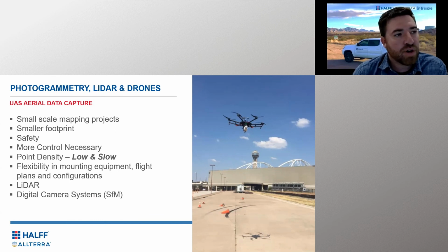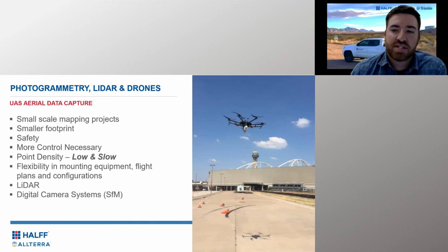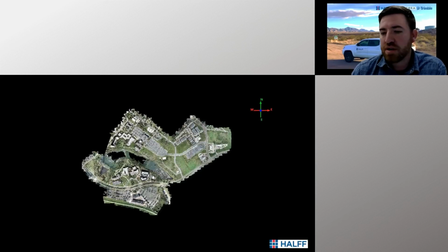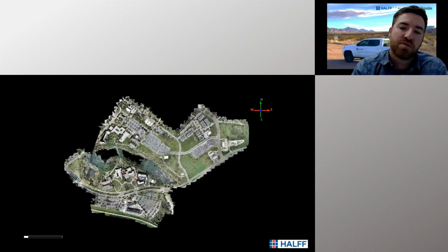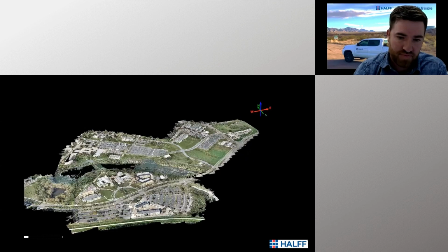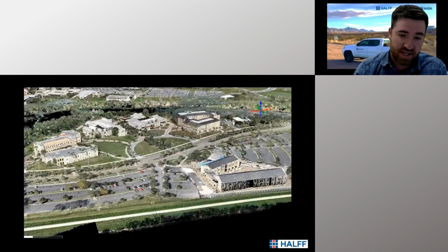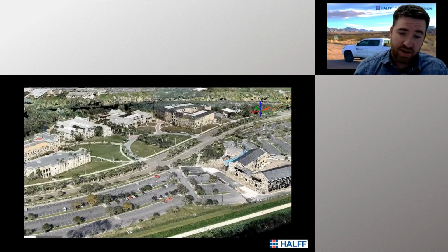There are times where, based on the elevations of the road and where the ditch elevations are, we like the ability to take the drone LiDAR out in the back of the mobile LiDAR vehicle and do some additional acquisition, low and slow, getting down into vegetated areas with the drone LiDAR to supplement our heavy mobile data set.